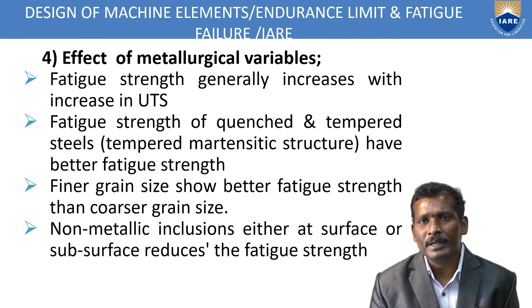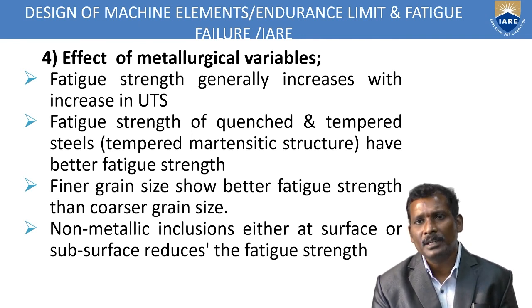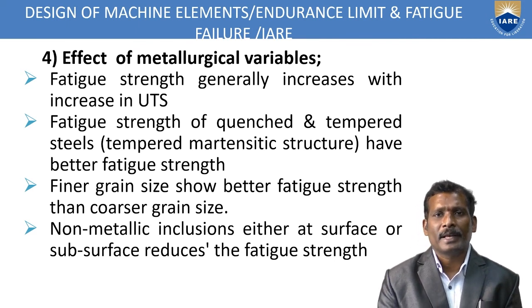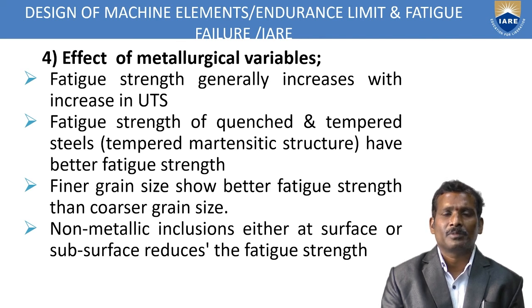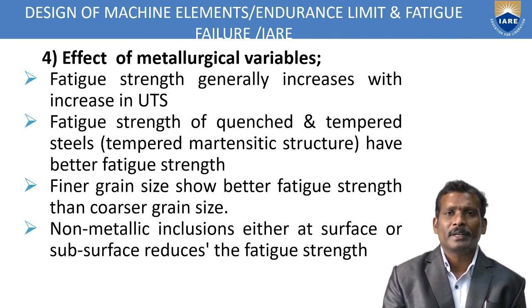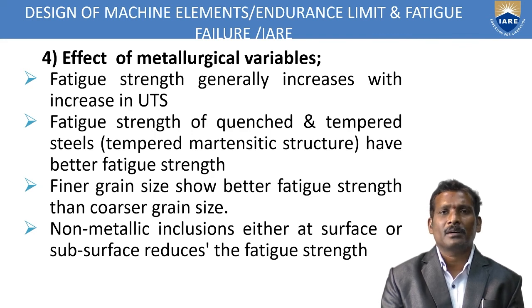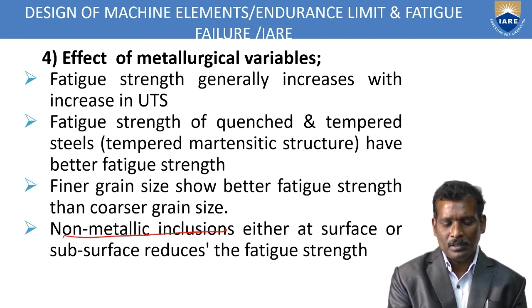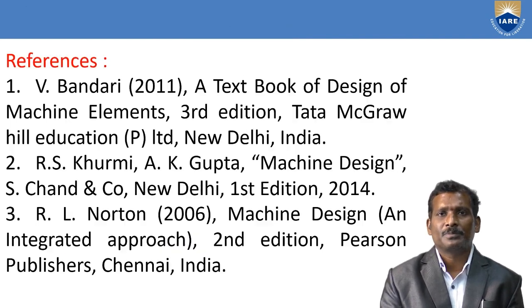So you can obtain a better grain size, that is, fine grain size, which gives better fatigue strength than coarser grain size. Whenever fine grain size is obtained in the component, then the component definitely has good fatigue strength. The non-metallic inclusions either at the surface or subsurface reduce the fatigue strength. So this is also one cause of failure.